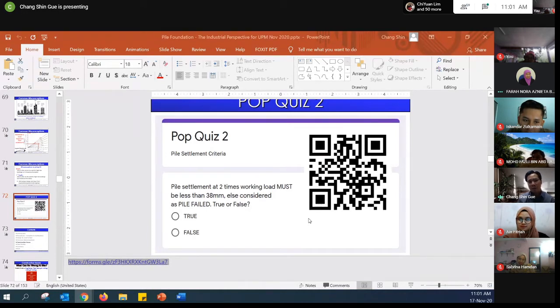So okay, for a small site, you maybe do one, or for a larger site, you may do two or three, and then you do the rest with the dynamic power test. Right. Okay. That means, say for example, if there is a site where they already did some piling before and it was left for some time, and then when we want to use the site again, the static load test is a must, isn't it?